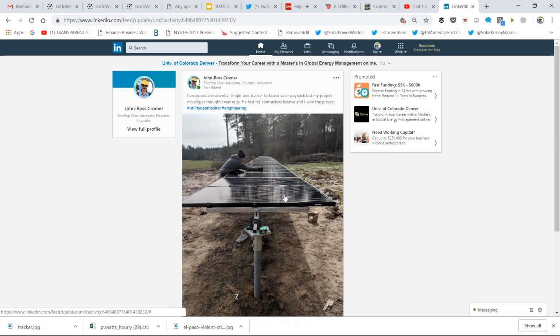This was a $30,000 residential off-grid project. So for about $2,000, or a 7% increase in the cost of the project, now the client gets to be able to face east in the morning to capture this eastward view, and then also in the afternoon when the sun is more up than south, he also gets that added production.